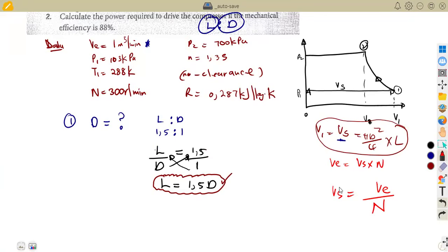So the relationship now, you check what you're given here. These are given as cubic meters per minute. So I said if this is in cubic meters per minute, your speed, best use it in revs per minute, so that per minute and per minute cancels.